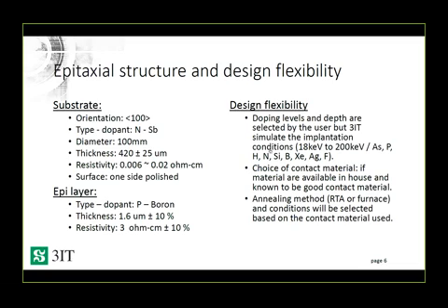Given that the design may change from one designer to the next, we are very flexible in terms of the doping species, level and depth that we can provide. This being said, we are limited to what our machine can do. We can also use double ionized species if the depth is not sufficient for a single ionized species. Another thing that we can change in the process is the material used for the contacts.